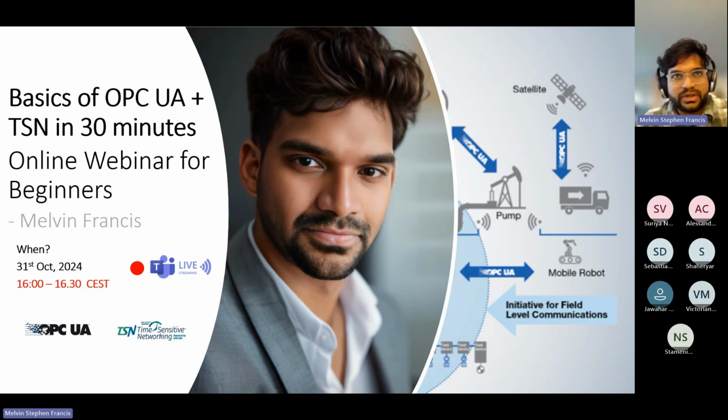So normally we are all familiar with how we can use OPC UA as client server communication. But today I will be showing how we can use OPC UA for the purpose of controlling IOs, motion control, and high speed networking with very good jitter performance, round trip time, and also how TSN is going to complement.